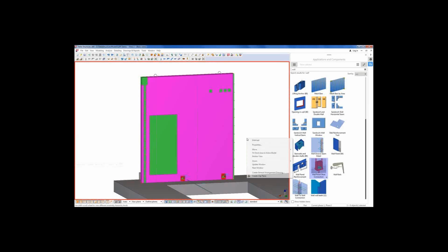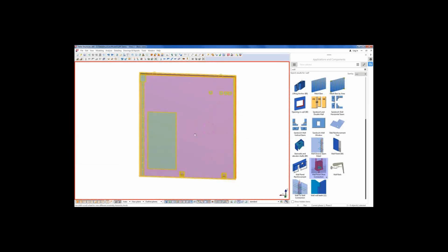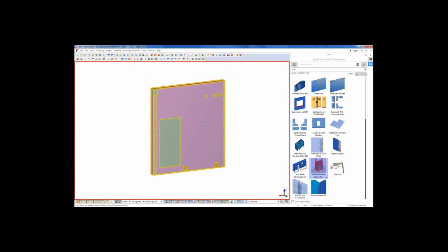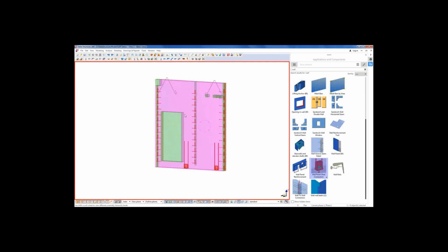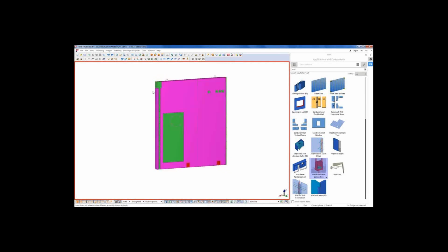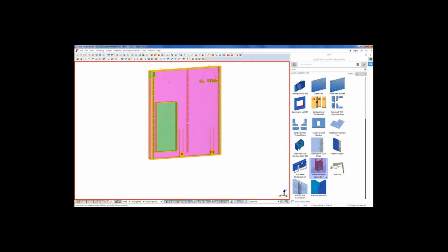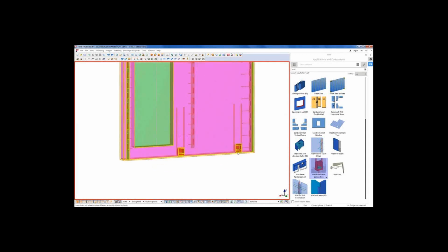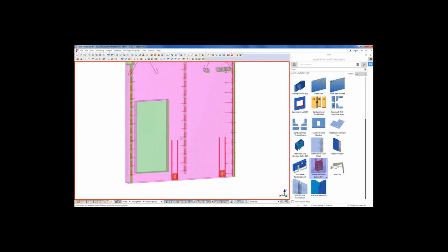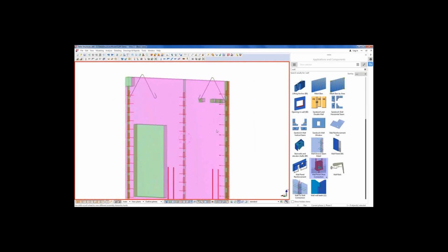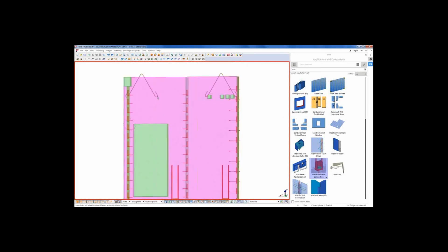Here we have it. So we redraw and see that this element already has all the shape, all the openings, and the openings are filled with green styrofoam. This is for the fabrication purposes. Also we have here these horizontal connection elements, the wall shoes, and also the vertical connection elements for connecting with other wall panels. And for the transporting or lifting, there are the lifting anchors.